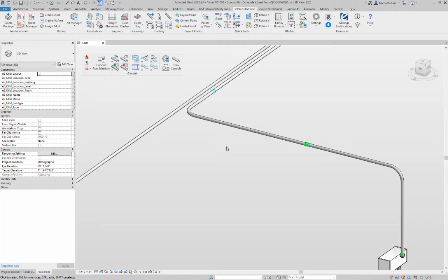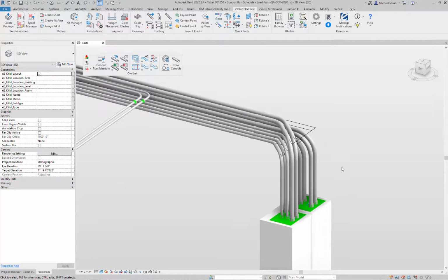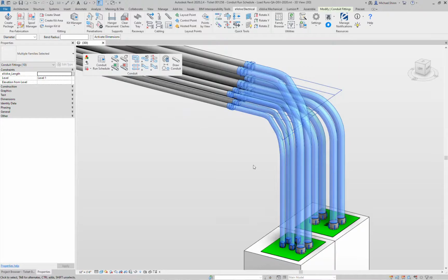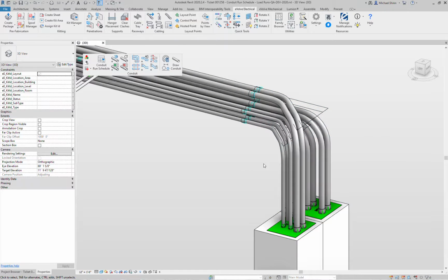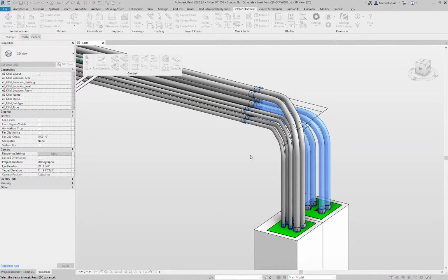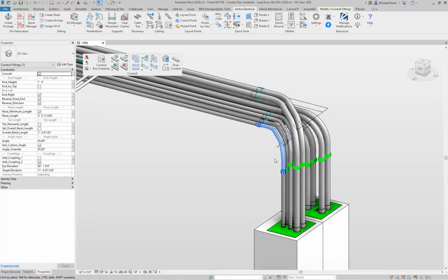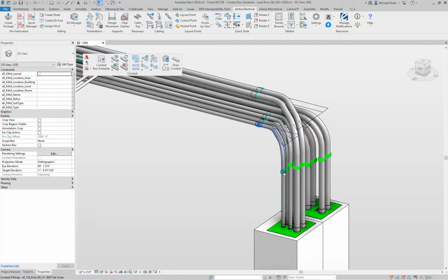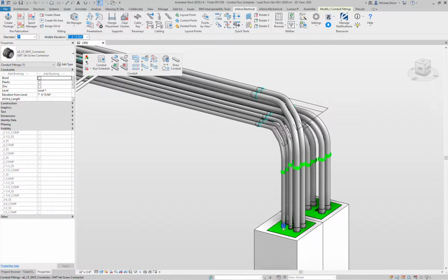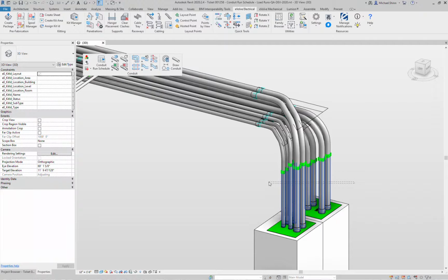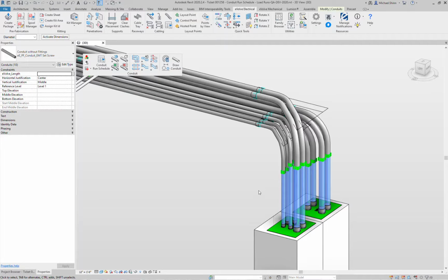So what the reset bend feature allows you to do is, after you've optimized this section, maybe you need to make changes to it and you want to revert it back to its regular native state. The Reset Bend feature allows you to window select a grouping of conduits or conduit bend families. Basically, it extends or retracts the tail and the nose back to its minimum state, and then it'll recognize, was it connected to anything downstream? Yes, in this case it was connected to that coupling, or that connector, therefore, please place in a straight segment in that scenario.